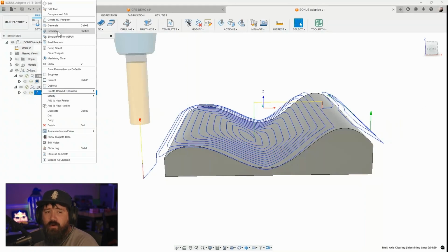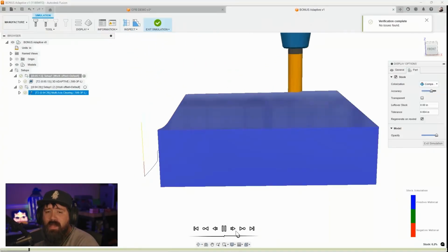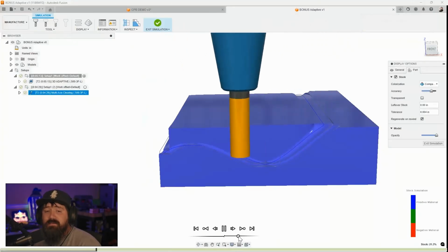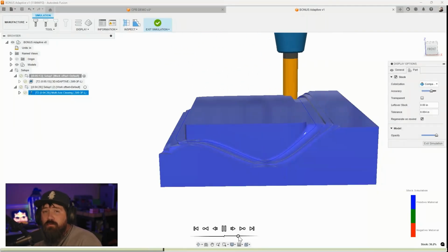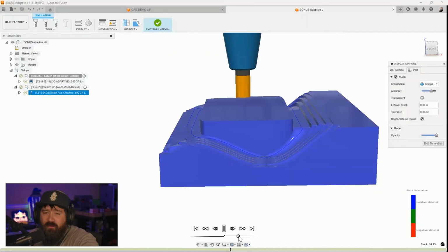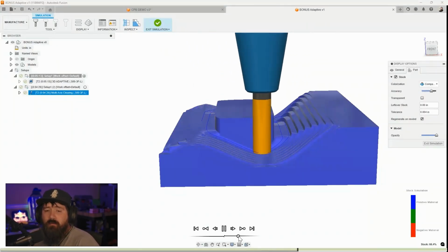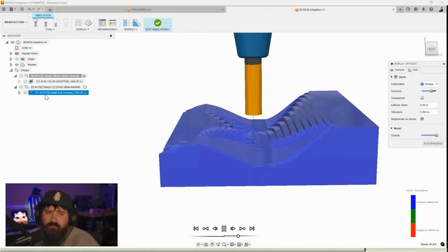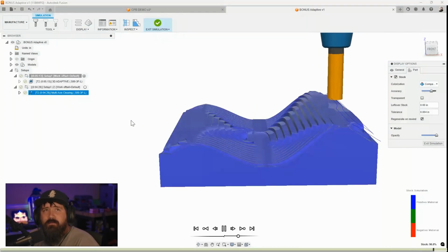You can see here in a little bit quicker of a time, and it's going to keep the tool locked to the floor, right? So as we go up and down here, you can see we're going to traverse, and we're going to do an adaptive here in 3-axis on this shape. So this is a pretty cool way to use this. Obviously, this toolpath could keep the tool normal to the floor. Obviously, we'd have a little bit of a limit here with a flat toolpath, but you get the idea of how powerful this could be for some of this roughing. And looking at the two of them, with similar settings, this one's about, I don't know, 30, 40 seconds faster. What do you think about this, Phil?